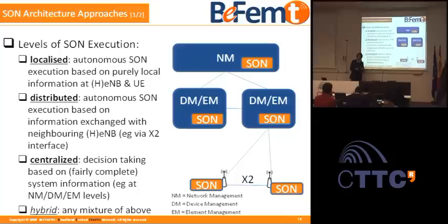Okay, so if you see that one of your cell users has a very weak field strength, which you get with the link quality indicator, you go down in modulation index. This is a local decision you want to take. There's no need to involve a central entity placed somewhere 200 kilometers from here. That's something very local. You can decide right there, and this is done today.